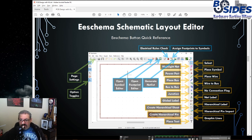So the next few buttons are related to hierarchical labels, or the hierarchical sheets. What this is, by default, you're working with one sheet here. Now let's say this one sheet is not enough to take our whole design, and we want to do a second sheet to show the circuits that are on a second layer of our PCB. We can create a second sheet by using the create hierarchical sheet button, and that's going to put a link on this sheet to that sheet.